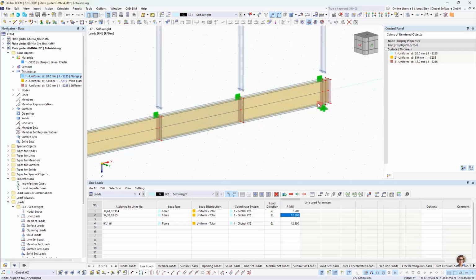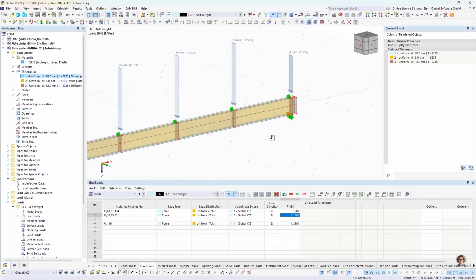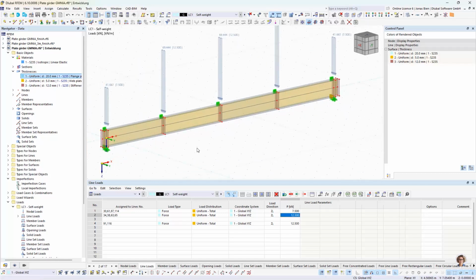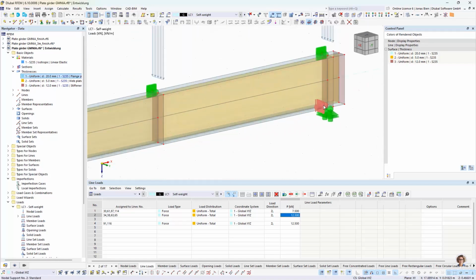Okay. Then I only need to do one additional modification of this mirrored part. I don't want to hold the plate girder in X direction on both sides. I don't want to activate any membrane forces here coming from large deformation in X direction. So instead of using support in X and Y direction here at the end node, I just copy the definition from above and just place a nodal support that supports in Y direction here instead. So it is free to move in X direction now.